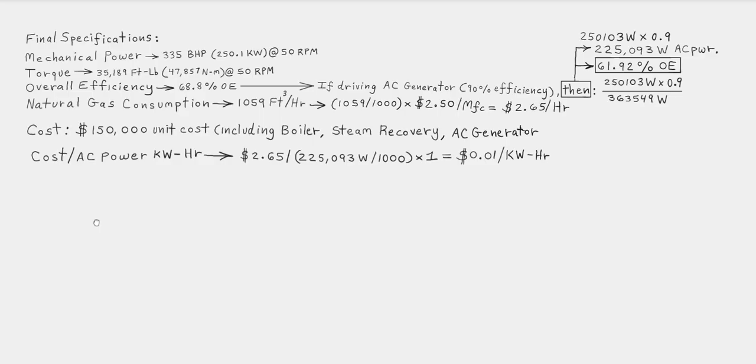So it would be basically like a frame design of thin plate discs, and then they could probably be completely filled with water with all the gas bled out, and that would excellently weight down the disc. And so depending on how much volume you put into that disc without any gas, it would be completely solid, and then we can get to 2,000 pounds of weight, because it's a lot cheaper to use water with bleeding than it is a thick plate of steel.